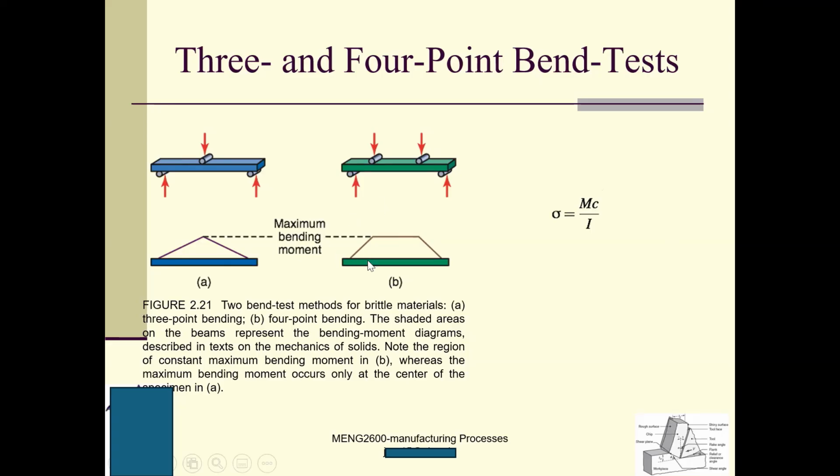Here, because the specimen will bend, in the middle is the neutral axis. Neutral axis means that if we put fibers layer by layer from the left end to the right end, and I press it, I know that on the top the fibers will be elongated, and in the bottom the fibers will be compressed.